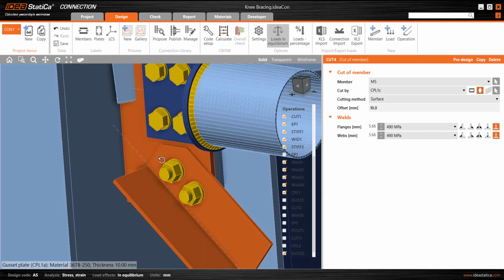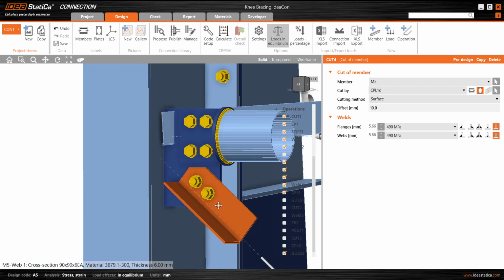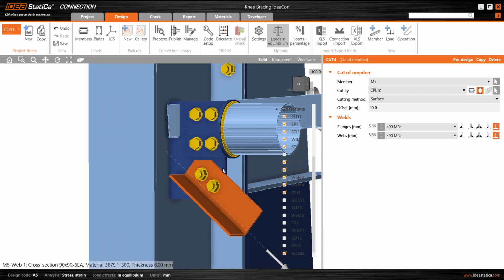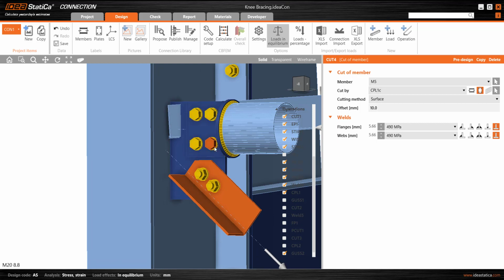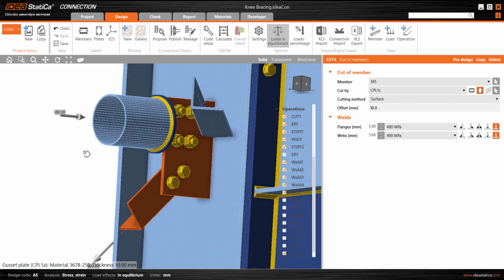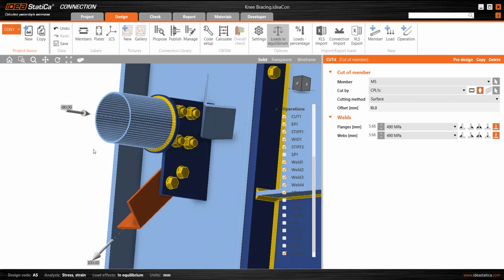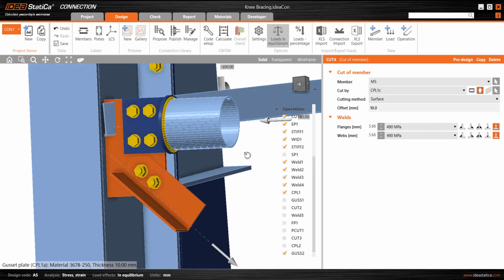So the beauty or the benefit of this type of method is that if the angle brace changes in angle or position, or the height of this tongue changes, this type of thing, that the cut distance or the spacing remains the same. And so that's quite a worthwhile option, I think, to do things like that. Also with plates, it doesn't have to be a member. You can cut plates with respect to other plates or members in the same sort of way. So I'm fairly happy with that connection detail now.